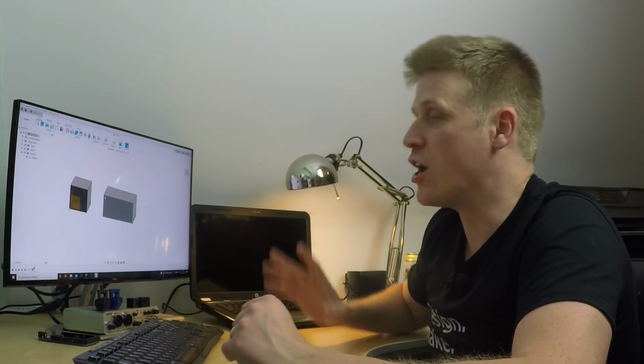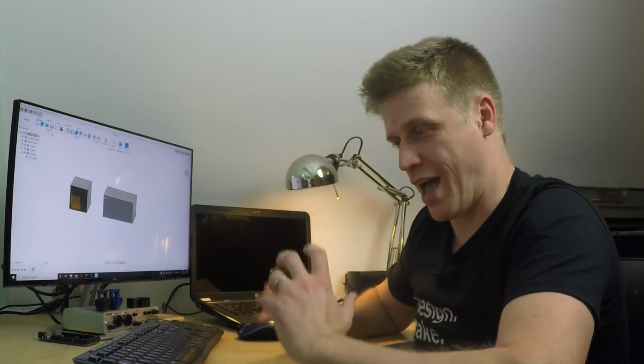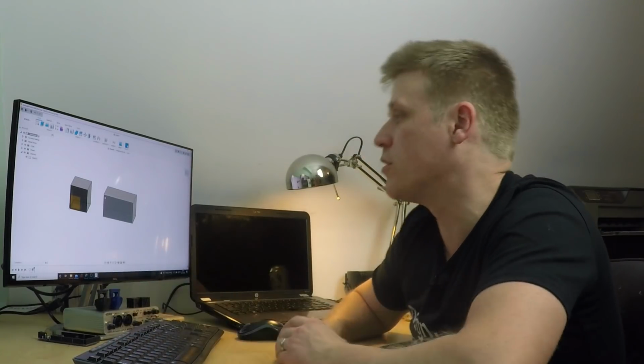Now, a word of caution with constraints: do not over constrain. The software won't let you over constrain, but only use them when it is absolutely critical. We're not doing things that are that complicated that we must have everything 100% constrained. If you're struggling to get something constrained easily, then okay, fine, move on, maybe come back to it, but don't obsess over it, because with lots of the stuff we're doing, it's just not worth the hassle, especially when we're not going to be going back and revisiting designs time after time to tweak them. We might get them pretty much straight right first out the box.